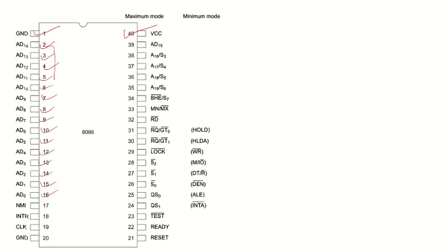This is the multiplexed address data bus, and this pin is also a multiplexed address data bus. Now this one is dedicated to the interrupt, and this is for the clock. And here we have two grounds, pin number one and pin number two. Actually there are two pins for ground to cancel the noise. We have also discussed these pins, which are called the multiplexed address status bus, and we have already discussed these status pins.